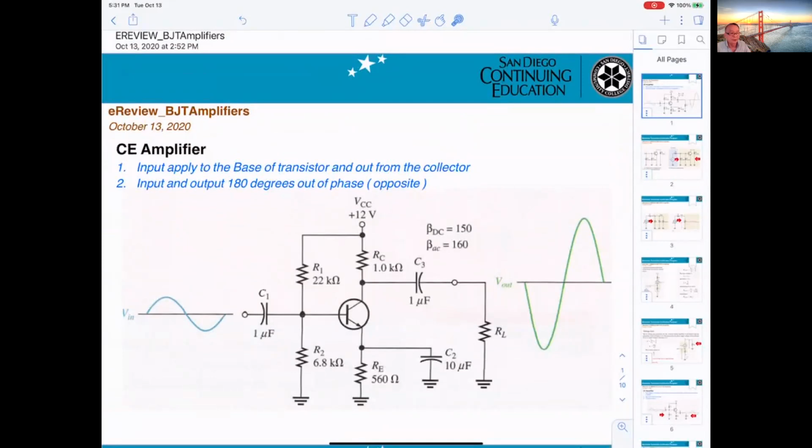In the past, you used VCC and VBB. Instead of a second power supply, which they don't want, they just use two resistors as a voltage divider. That's how you get a voltage at the base without another power supply.